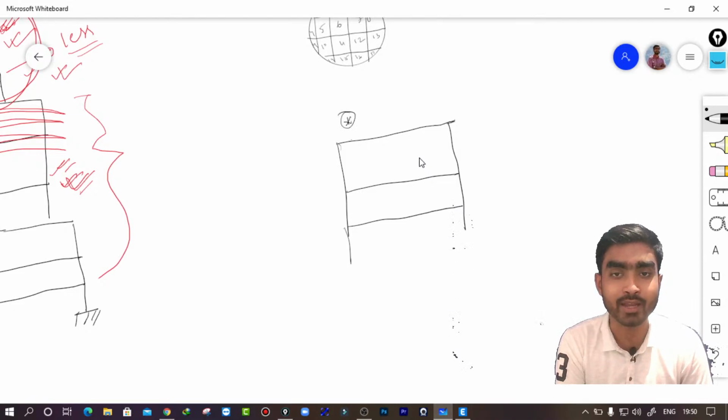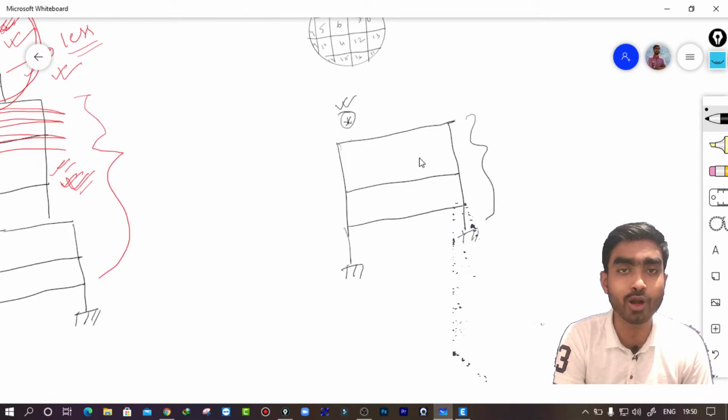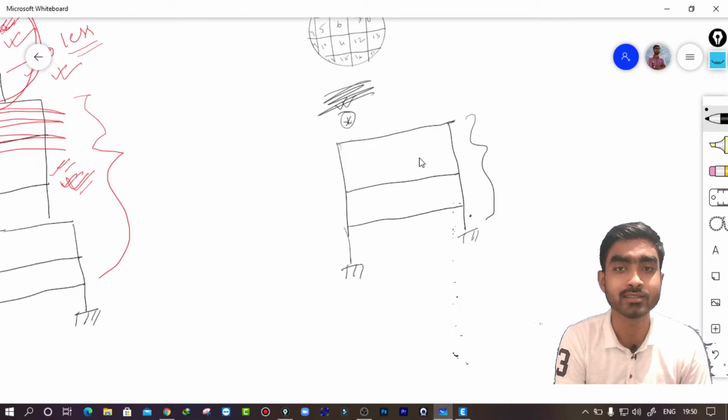Now what will happen when you are using eigenvector analysis? It will calculate the mass matrix for this small node also, and when it compares it with the total model, you will see this small node is vibrating with a higher frequency as compared to the structure below.